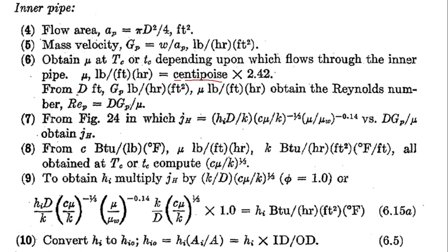And next, from the diameter, which is given in feet, and from the mass velocity and from the viscosity, you have to determine the Reynolds number.